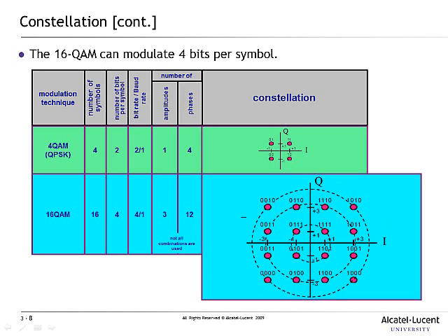So in the case of 16 QAM, we have 16 possible phases. The ones in the center here are very similar to QPSK, so 4 different phases, all of the same amplitude, and then you have another set of 8 phases outside that.